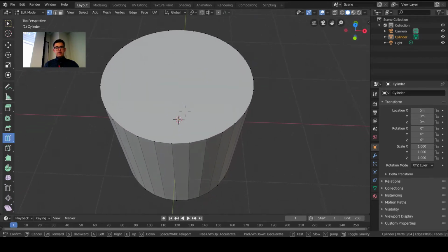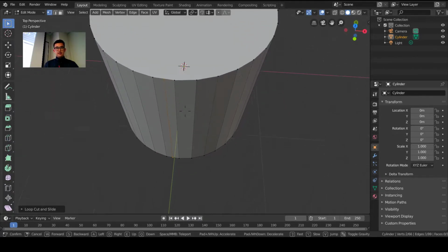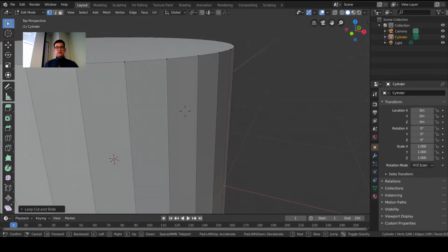Okay, so here I'm flying around and getting to different views. Okay, so when you cut things, you have to do it on each plane individually, if it's not a similar plane. So let me make this the kind of cut I want to make, and then I'll make a cut across the circle also. So I'll just left click this here, and now you can see I've made this cut here.